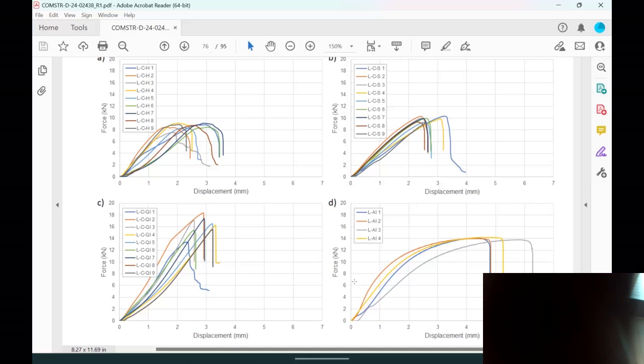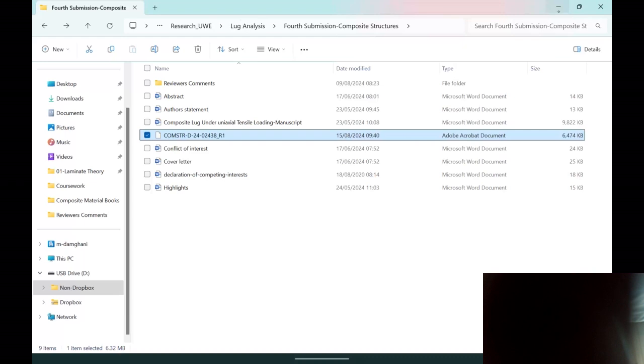But you can see this is quite linear. That's typical of carbon fibers. It's very linear behavior, linear elastic, as we said. If you look at the aluminium, up to a point it is linear, and then it becomes non-linear and necking down, and the different failure mechanism. So it takes a lot of energy to make it break. But for the composites, it just goes to the max and then bang. You hear a bang noise. Okay. Just to show you how different stacking sequences impact the behavior of the composite.